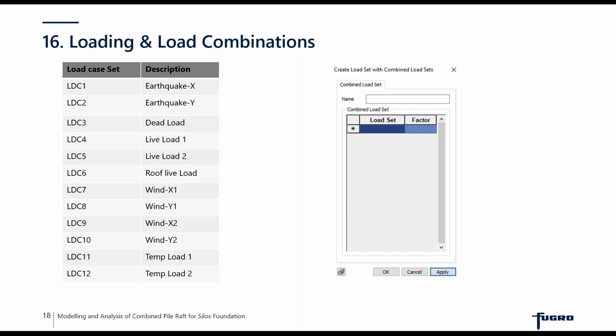Based on the initial structural analysis done, you can always decide on the most critical load combination, which can be the case where you have the maximum reaction on the pile, or the maximum load sharing contribution coming from the pile. Decide on the serviceability load combination, create the combination in MIDAS GTS NX, and then you can run the serviceability criteria here in MIDAS GTS NX.